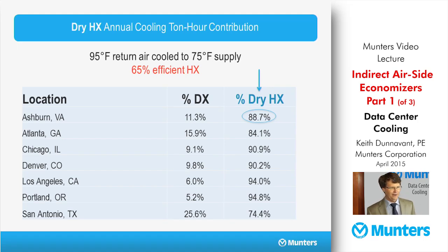If you add all of that up, and if you're operating with heat exchangers that have no more than about 1 inch of water column peak pressure drop, you're going to achieve that heat rejection at 0.25 kW per ton or lower. So pretty efficient compared to most refrigeration systems, which are at best about 0.75 to 0.8 kW per ton on mild conditions and over 1 kW per ton on hot days.